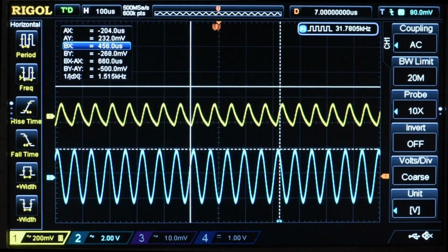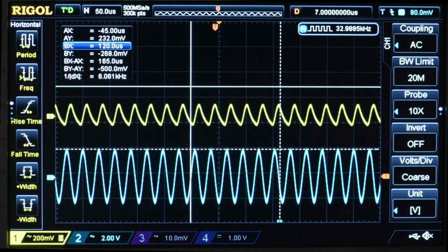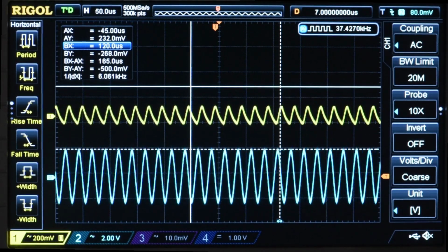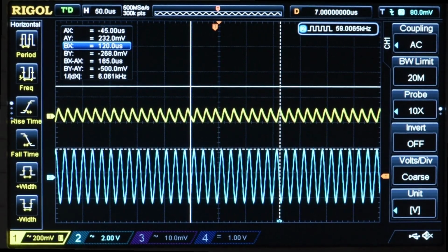I really don't want much above 30 kHz getting through. If I use this as a load on a switching power supply, I don't really want the switching ripple to affect the load level, and I still have quite a bit of signal getting through even at 60 kHz. No problems, except at this sampling speed, I won't have time to do much of anything else.